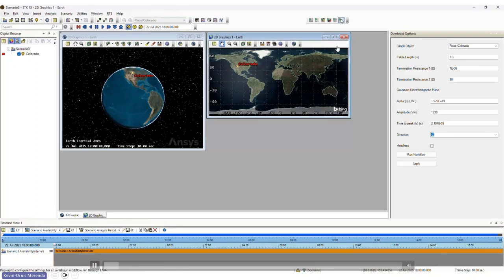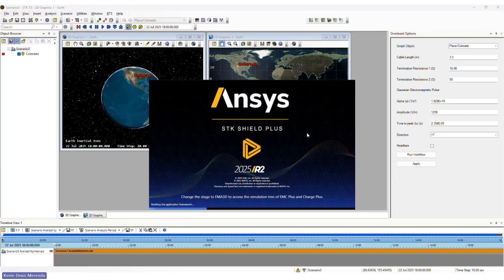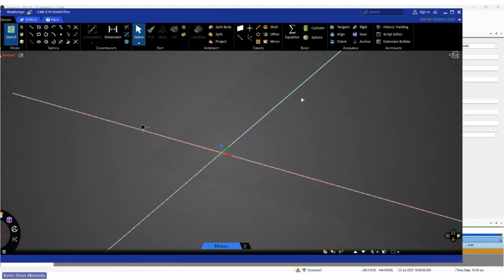So we click the workflow here. We set up the various parameters. Select a direction. This is important because our workflow automatically creates the test bench that we're looking at with a ground plane and then electronic boxes on the top. And that is going to be on the minus Z direction, the ground plane. So if you shine a source from the minus Z direction, there's not going to be any coupling because of the ground plane that is present. So always select one of those good selections.